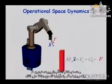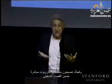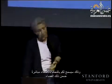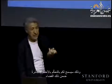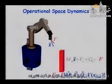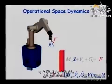And then you can control it. You find your F, you multiply it by J transpose and transform it into terms of torques. And suddenly now you are directly controlling your robot in operational space, in the space of the task. And that would allow you to control directly your errors in that space. So your force control will be a function of those estimates, in the same way, with the same structure that we saw just earlier. Okay?